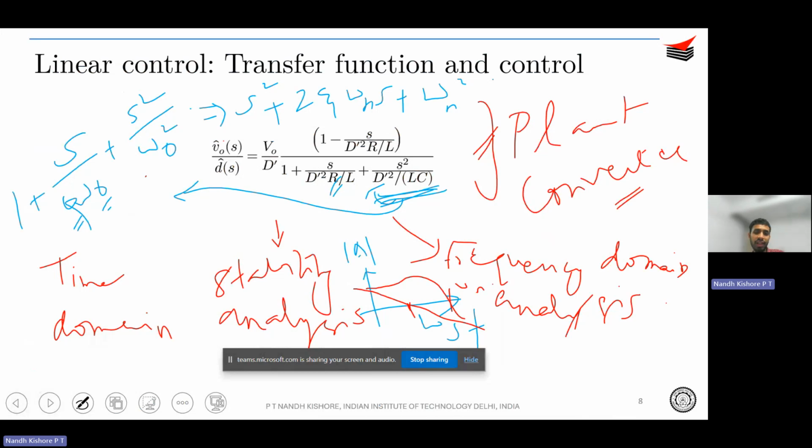It's not just that we design the converter and do switching. We want to run it in closed loop, right? Of course, you understand that over here you can change the duty. If it's open loop, you can just change the duty from 0.5 to 0.8 or whatever. But while it is running in an actual converter or system, you cannot go and manually change the duty every time.